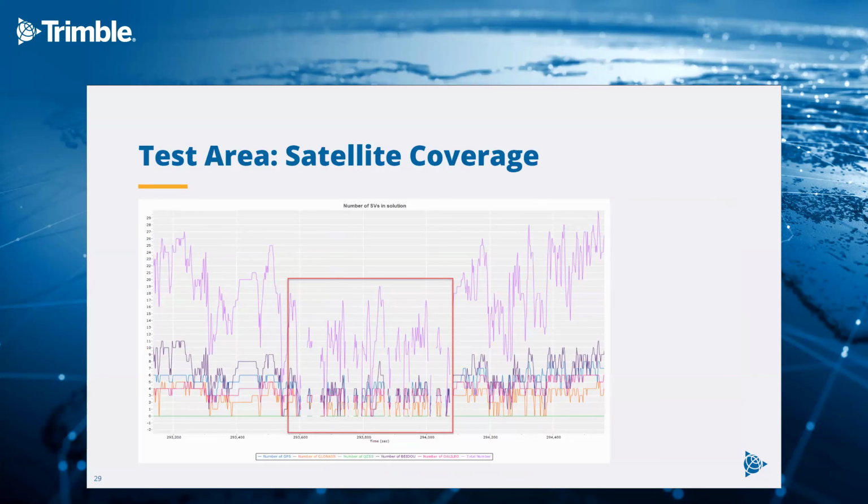So the GNSS-INS trajectory, also known as the SBET, smoothed best estimate of trajectory, underwent post-processing in the latest Inertial Explorer single base mode. That supports all of the signals and frequencies right now, but with a maximum baseline of 3.5 kilometers.